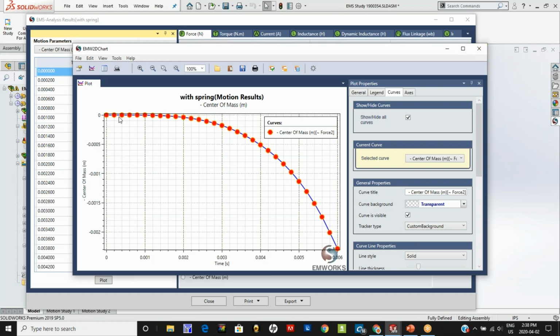And you can see the movement is not linear like the voice coil actuator. That tells you that the force variation is very large in a solenoid type actuator. In a voice coil actuator, the force is more or less constant, so it's moving under a constant acceleration, and hence you could see a lot of linearity in the response. It's not the case with the solenoid.